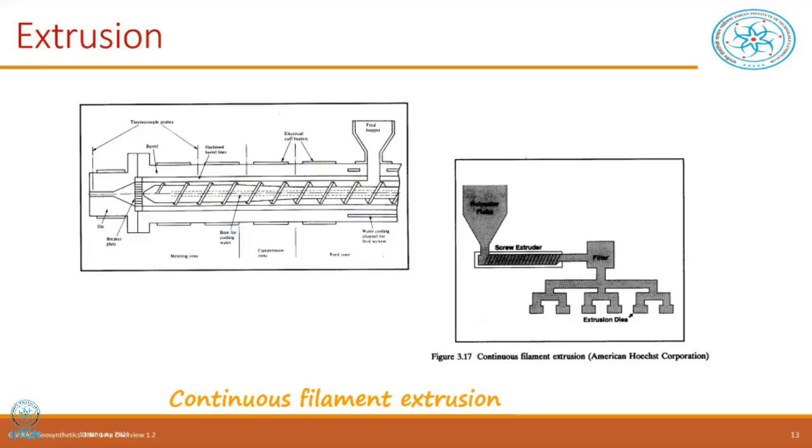Okay, so obviously this filament is circular in cross section by and large, not always, but by and large. That means it's cylindrical in shape. And what else do we do? We have to also think that even in other forms of yarn making, even when you make cotton yarn, after making the yarn you always pull along the direction. That is called drawing. So mind you, we are using a word called orientating here because of polymeric material. These molecules, instead of being randomly oriented, are pulled along the actual direction, and that gives us the increase in strength.